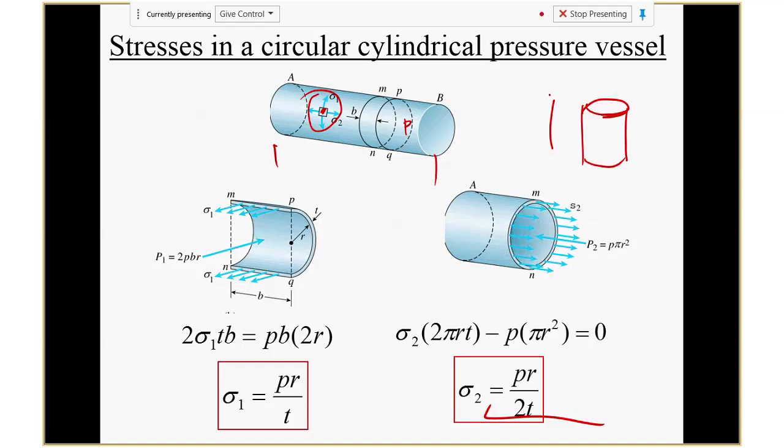Okay, so remember the wall thickness is really thin, and we talk about that situation. For a tube, you're going to have circumferential stress, and we call it... anyone remember the term we gave it? Hoop stress. So it's a hoop stress, or sometimes they call it Laplace stress. It's the same thing. And that's given here, sigma 1. That's the circumferential direction. So you're going to have the stress determined by pressure, radius, and the thickness. So that's the way you can estimate the average stress there. Again, that's an average stress in the wall, across the wall thickness.